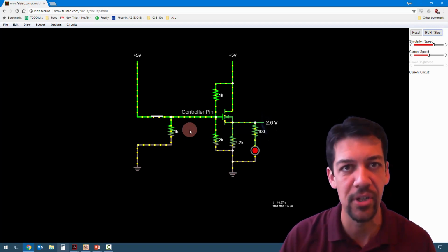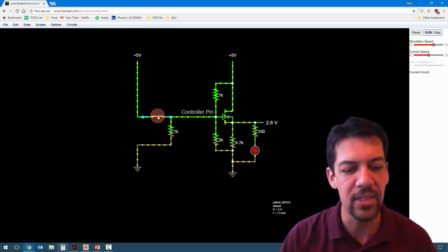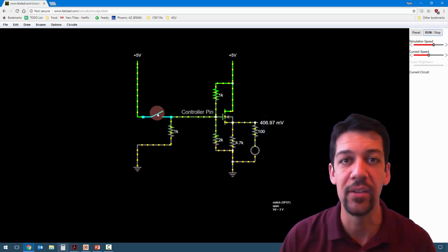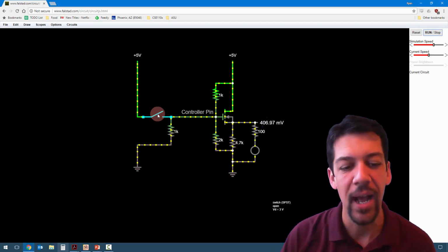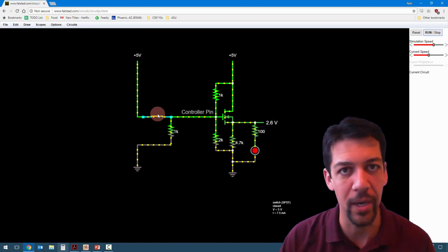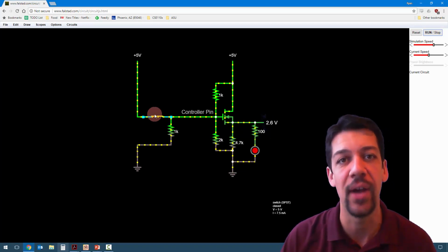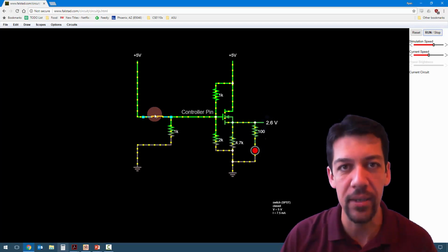In this configuration, a pull-down configuration, this is what's called an active high configuration. So when the switch is open, when it's inactive, we read a 0. When it's active, when the switch is closed, when I'm pressing it, when the action is happening, I read a 1. So this is an active high configuration. Now let's look at a different configuration.